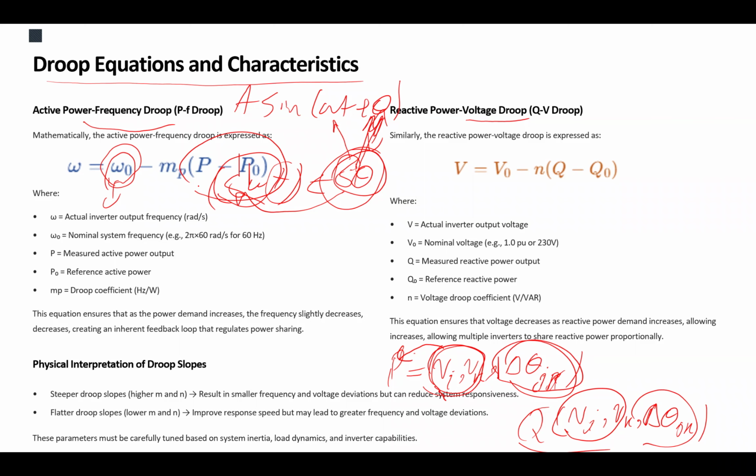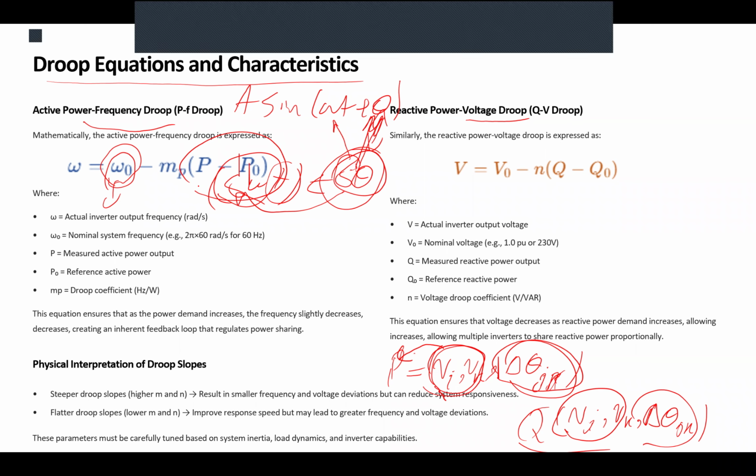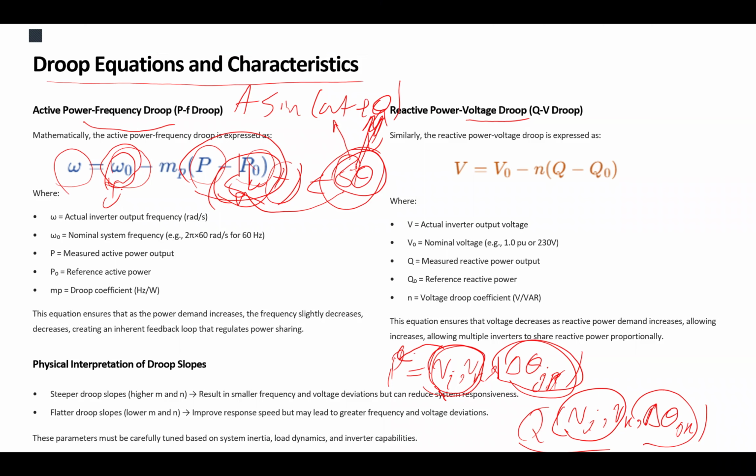So now that we translate that phase difference into a frequency difference, we could relate the deviation in active power into the deviation in the frequency. We measure a frequency, we measure our active power, we have set points for both of them decided in the control system. Now, if there is a deviation, we are going to eliminate that difference. Make sense? Like a PI controller.